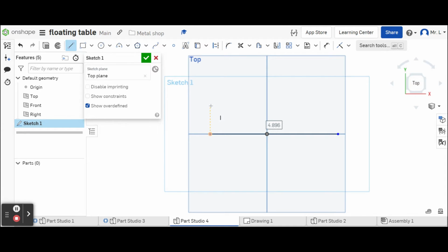Now we're going to draw two vertical lines. You're going to light up one of the endpoints, and I like to start on the left, kind of go left to right, like you're reading. And we're going to do the same thing. We're going to light this endpoint up, and come across until we get these broken yellow lines that go from both endpoints. And we're going to drop down. I'm going to swing over here and light the other endpoint of my vertical line up and bring it over. So now the endpoints of these two lines are tied to each other on both ends.